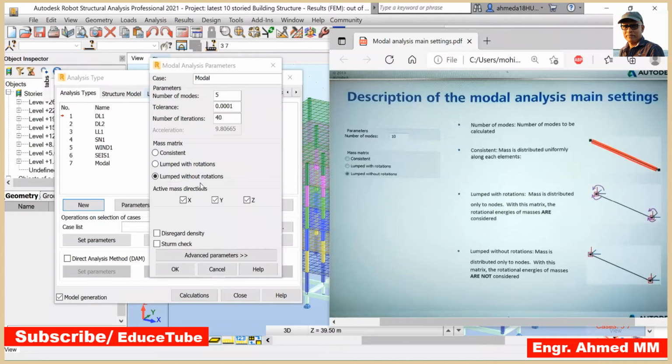Even this mass matrix, the consistent mass matrix, gives more accurate results. But when we use a lumped mass matrix, basically what is happening in this situation is that a portion of the structure's mass is allocated to the supports and therefore not taken into account for seismic calculation. Very important point for these two.